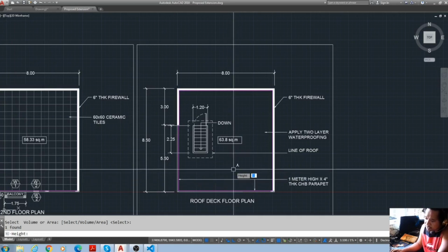Of course, the second is it will ask you to input the thickness or height of the concrete. This is the slab, so this is more likely 0.12, or 120 mm. Since I am in meters, if you remember my units before, I will be putting here 0.12.